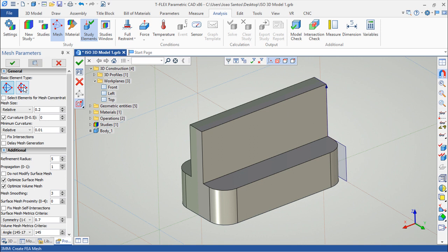And the main difference that we can have in these different types of elements is that the curvilinear type of mesh is more suitable for curvilinear geometry. The setback that we have in this curvilinear is that we will create more points, we'll have a heavier mathematical mesh and model, and it will take more time to make the necessary calculations. On the other hand, the straight edges finite element has nodes only on the vertices, and it's a lighter model.